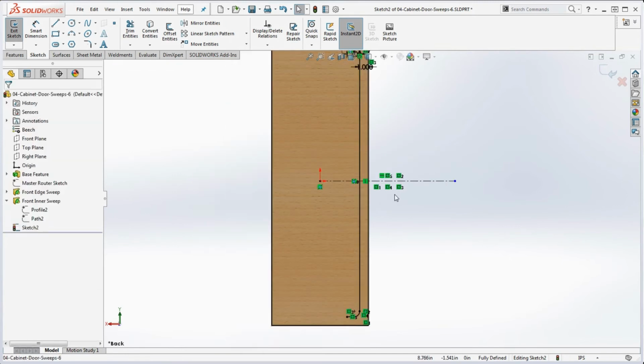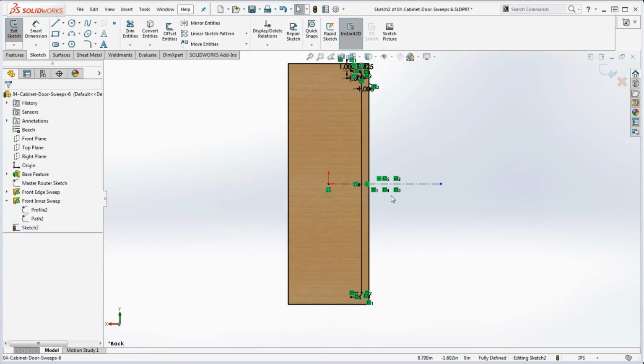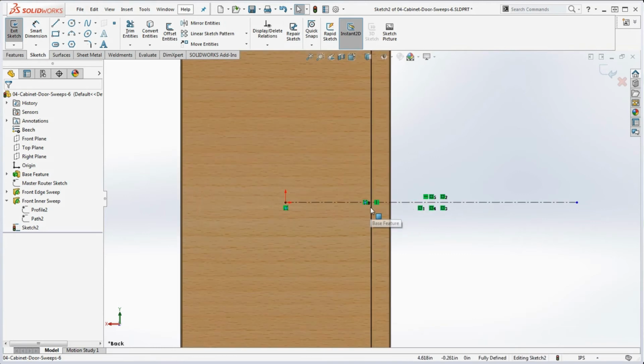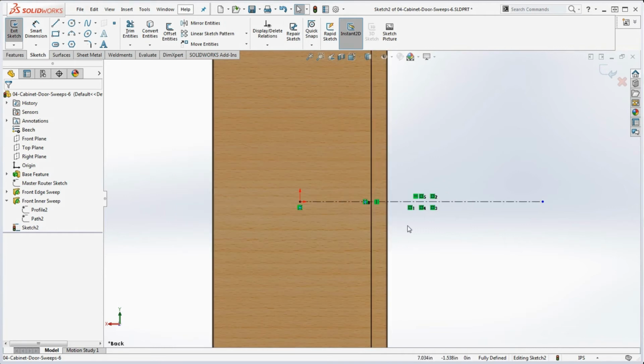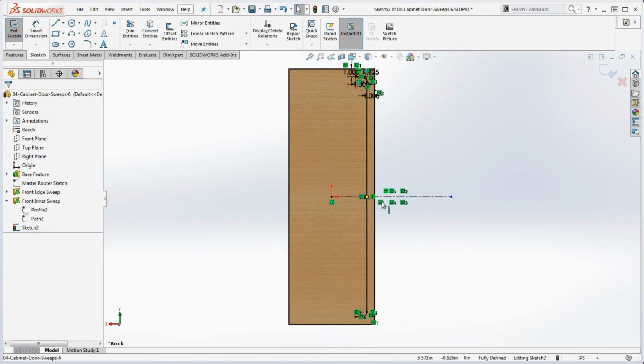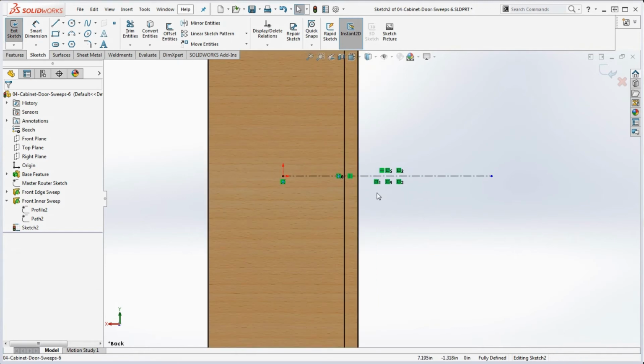I don't know if there's going to be a consequence to leave it in there or taking it out, but we'll soon find out. The problem with having points kicking around like that is sometimes you change the sketch geometry. These points start going under-defined, and they're really hard to find. So, they may not be apparent. They might be buried on the line here. They might look like they're black, but they're really blue because they're really small, so they're hard to see. And so I just deleted it.